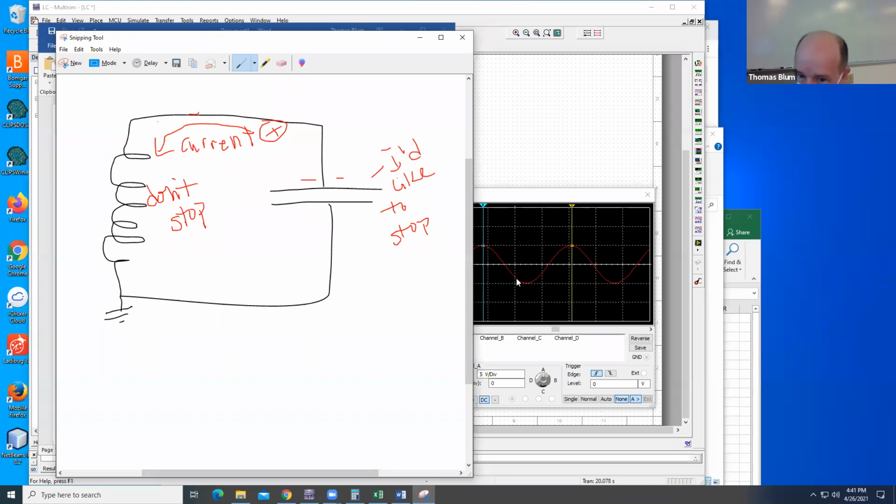So now we're in this negative part of the cycle. So now the voltage across the capacitor is negative because it's starting to charge the other way. And then it gets all charged up with positives on this side and negatives on that side. Now we're here, and it starts to discharge all in the opposite direction. And that's the oscillatory behavior, back and forth.